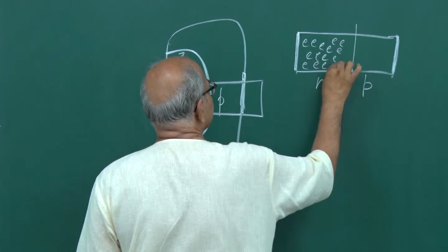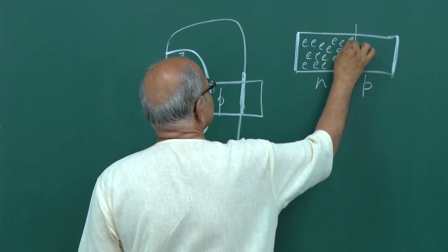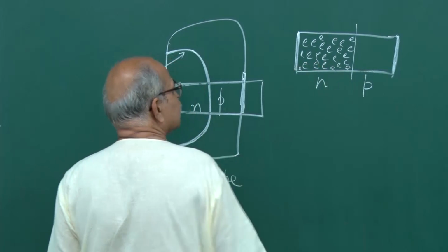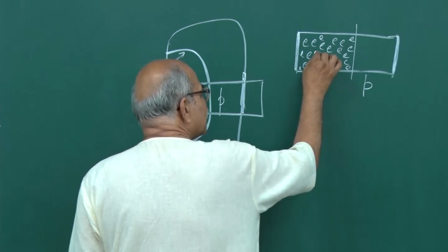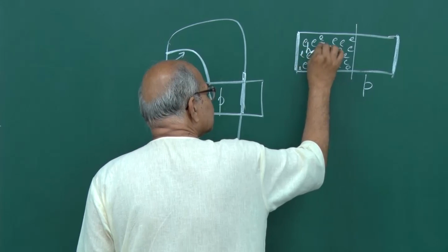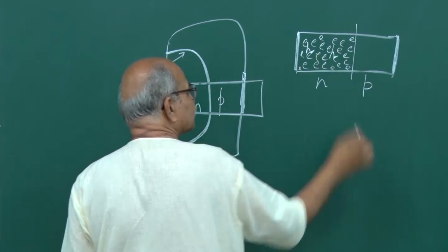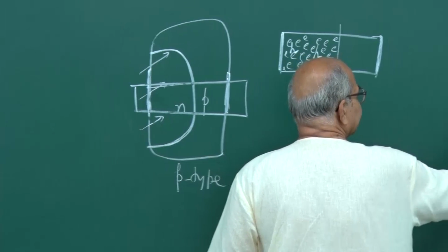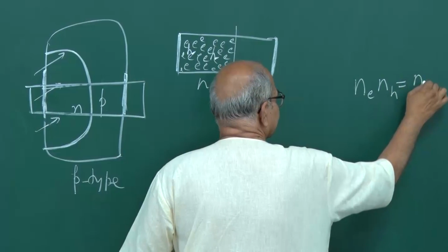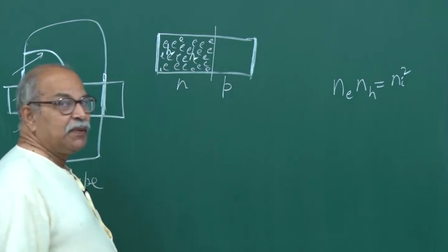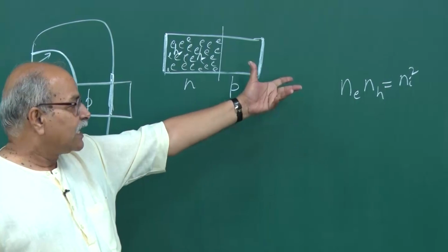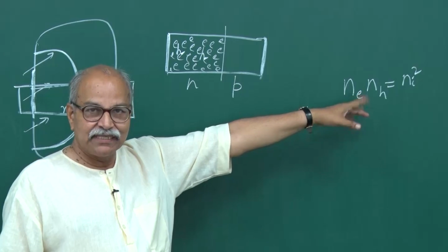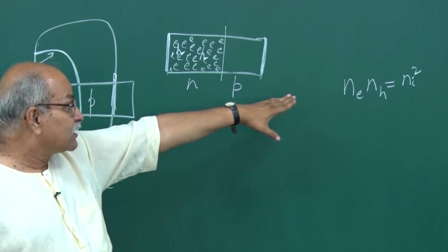Because of those pentavalent impurities, you have a large number of free electrons here, and you have some holes here in between, a small amount. Remember, n_e times n_h, that is fixed, n_i squared. And for a ppm type doping, we had calculated that the number of holes reduces to a few thousands per centimeter cube, but they are still there.